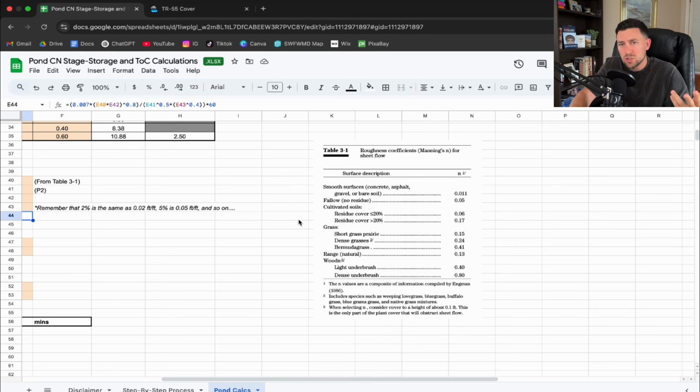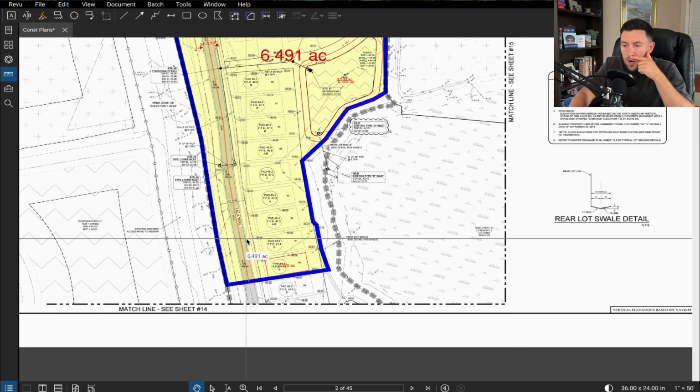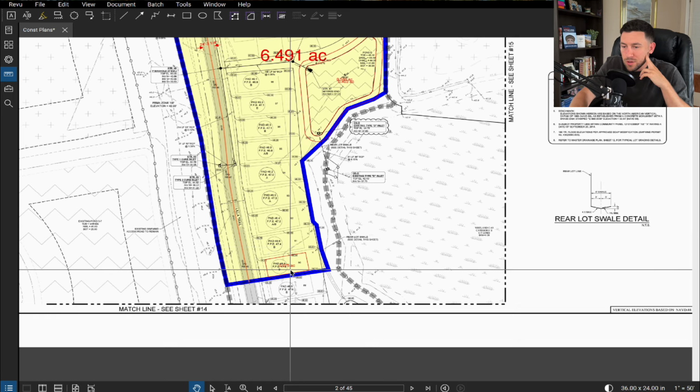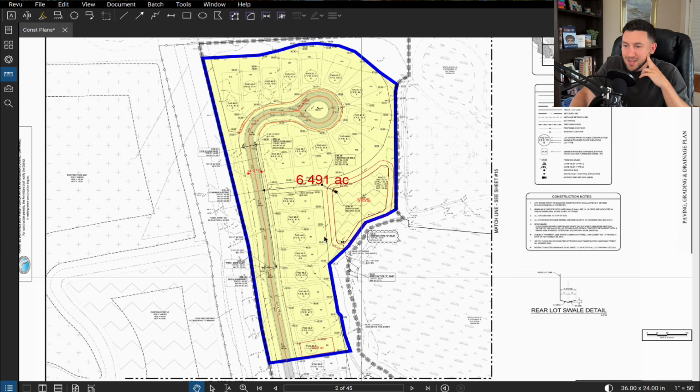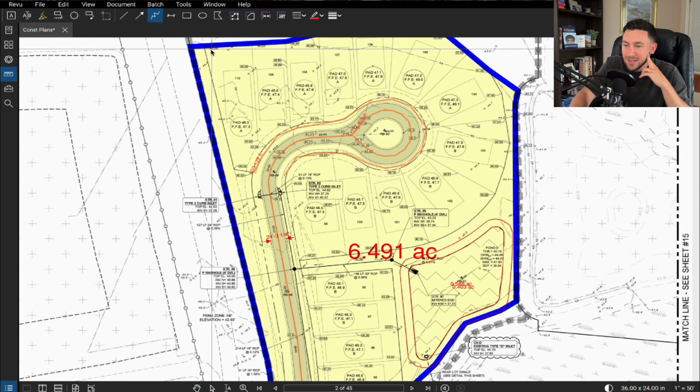How do I know where to start the point? That's a great question. Where will the furthest little rain droplet fall and then go into our system? It looks like a couple of places. I'd first start maybe right here at this high point. Looks like a water droplet wants to fall here, fall there, and go there.